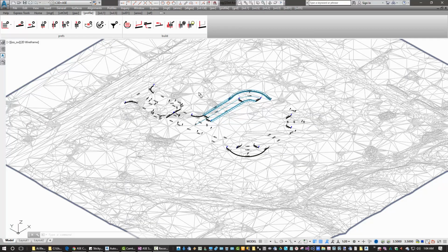Okay, so now that I've created a profile data with these design markers and paving features and automatically generated this corridor model, I'm going to now generate the finished ground profile output that we're going to put on the sheets, the improvement plans. So I'll need to create a new drawing dedicated to this alignment, which is alignment 4.